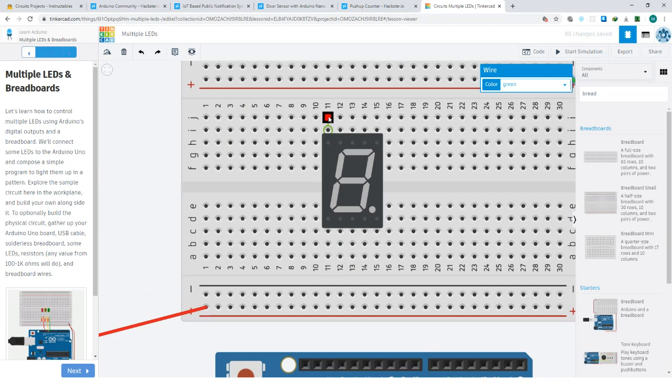You see, we'll be using pin 11 there, and number 12, row number 13, row number 14, row number 15. So we know what we'll be dealing with. In our case, we said the one in the middle is the common one. So definitely we are going to take a cable from here to connect to the negative. Okay, let us put it there. And this one, because it's a negative, we put it black.